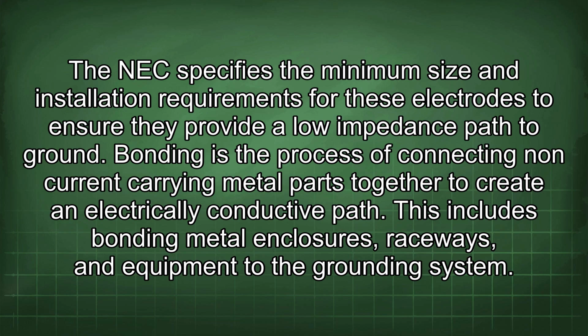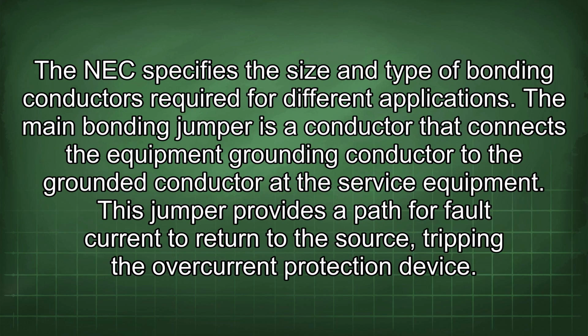Bonding is the process of connecting non-current carrying metal parts together to create an electrically conductive path. This includes bonding metal enclosures, raceways, and equipment to the grounding system. The NEC specifies the size and type of bonding conductors required for different applications.